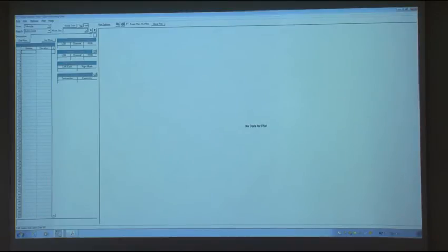Basically, right now, because we have not entered any data, the first thing you have to do is choose which river and which reach you want to enter data for. You can see the list of rivers. If you click on this one, you see we have the option for the Fall River or Tributary. So let's select the Fall River. And the reach, if you select that, we have two options, the upper reach and the lower reach we entered before. So let's select the Fall River and the upper reach, okay?